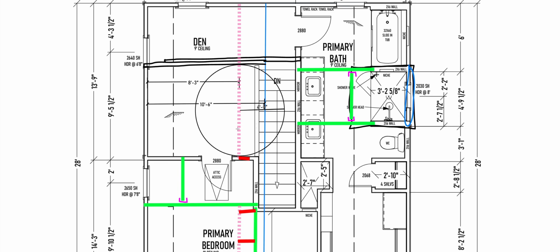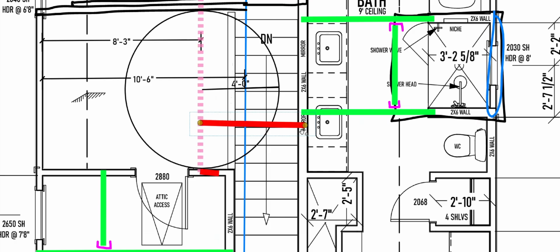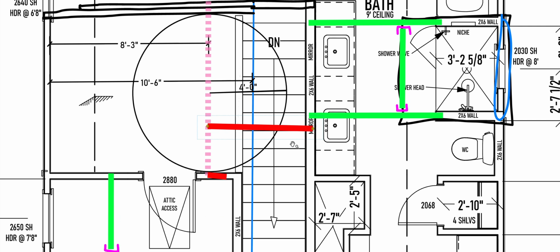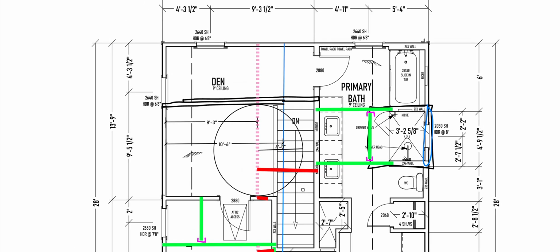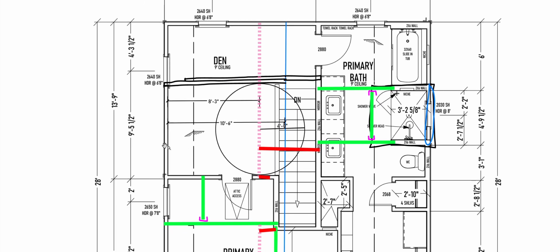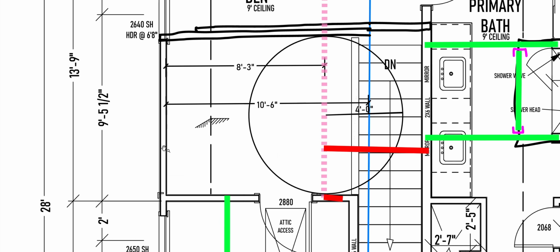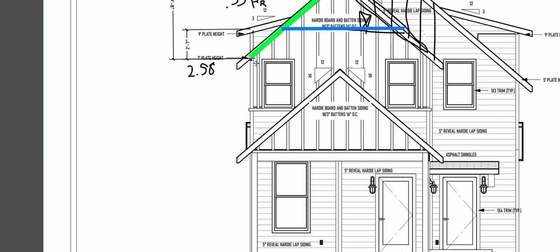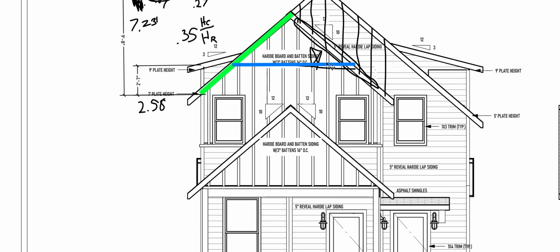Do I have the ability, first of all, to brace over to this wall? Because if I can, that's great. If that's not more than 45, I would like to do that. Now that does look like a lot, but we have a steep pitch, so maybe it's possible. Maybe it's not. Let's analyze. So here's how we'd analyze. This roof starts at 7 feet. 7-foot plate height is where this roof pitch starts. I know that wall in there is a 9-foot height.